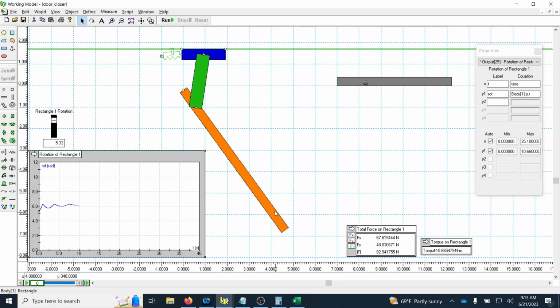We saw how much force it would apply to the door when there is very little damping and high stiffness in the door closer. And we also saw that if you don't have a spring in your door closer system, the door will never close. It will stay at its initial position. So the idea that there is no damping or no spring in the system is not accurate.